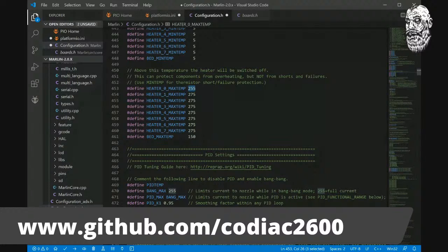They'll say E3D V6 capable of printing up to 450 C, asterisk, only if you have the titanium heat break and the copper block and a copper nozzle. The brass nozzle isn't good past 300 C. The aluminum block begins to expand after 280 degrees C, so it begins to loosen, and your nozzle can actually fall out mid-print.